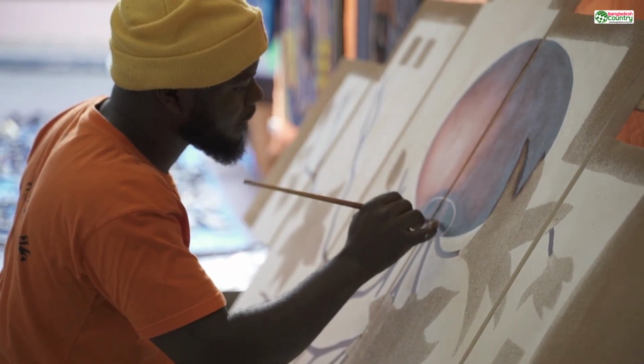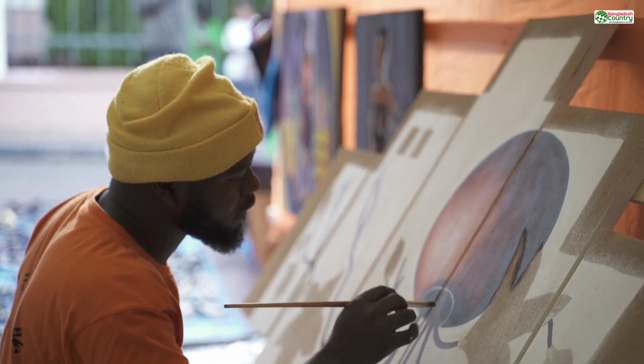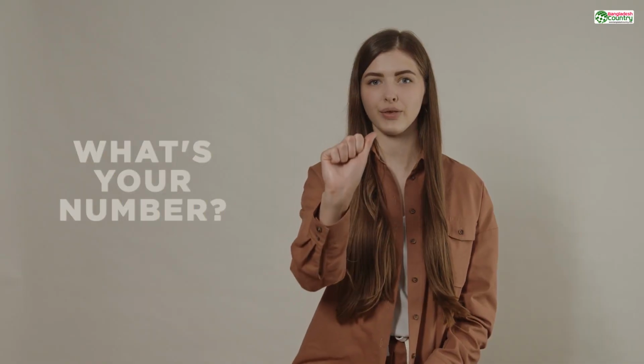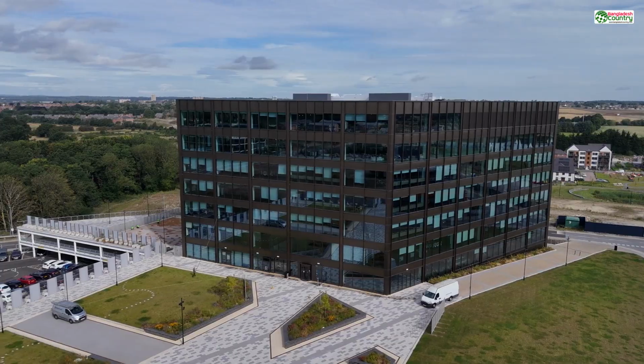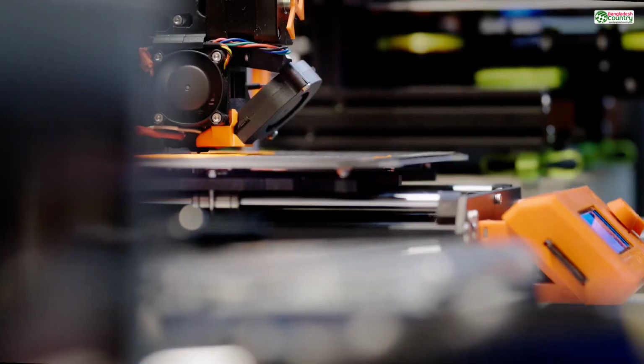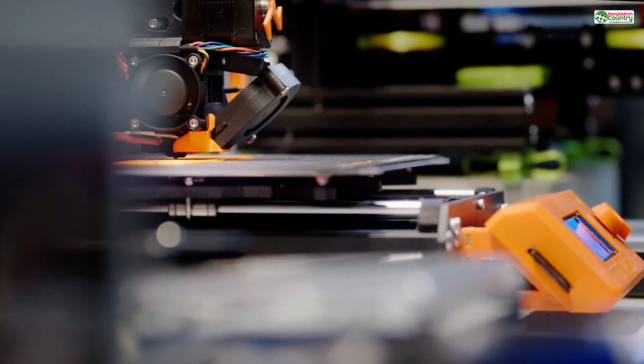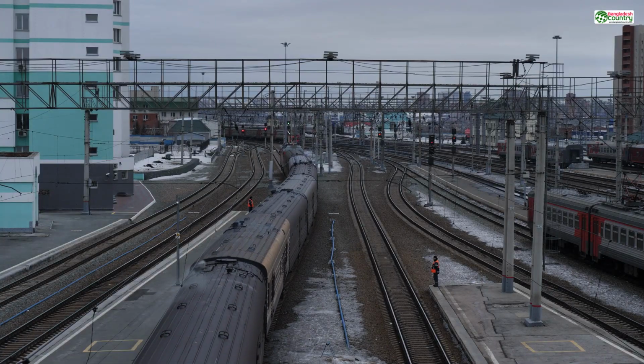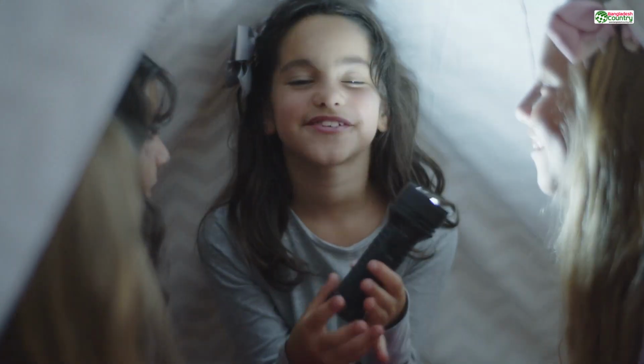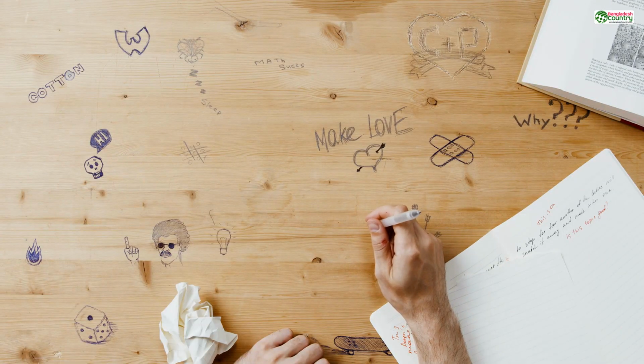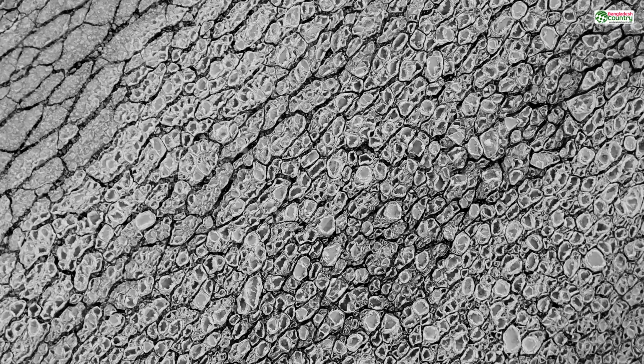Imagine building a sculpture out of stacks of paper. Layer height is the thickness of each individual sheet of paper. If you use thick construction paper, your sculpture will grow very quickly, but the edges will look blocky and rough. You'll see those distinct steps. Now imagine using incredibly thin, fine sheets of vellum. It will take you ages to build the same height, but the final surface will be incredibly smooth, with curves that flow almost perfectly. That's precisely what's happening inside the 3D printer.